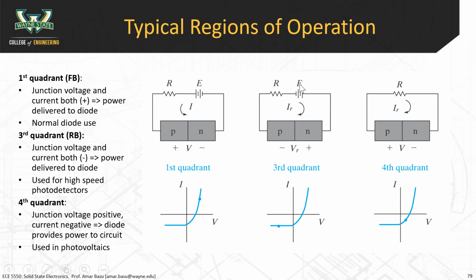All right, so you put it in reverse bias like this. You might have some resistor in your circuit. Here's the thing. Now we've reverse biased the diode, and what does that do to the electric field in the junction? Well, if you reverse bias the diode, it makes the electric field in the depletion region stronger.